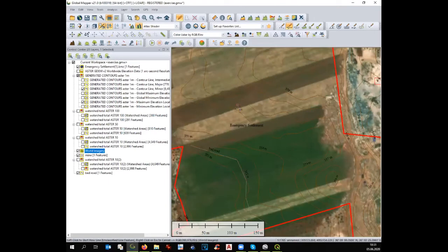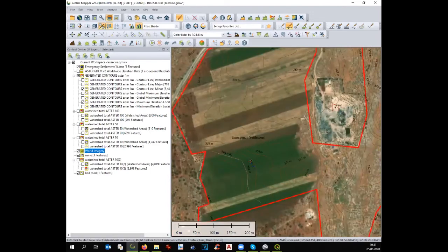If you put a road there, what happens? The water is going down here, and the road is going to be like a dam. It will block the water. So that's not a good thing. Then you need to make a culvert every 5 meters for protection. You have to try to put the road in a way that you don't need a culvert, and you have to try to put a road where you have the peaks.